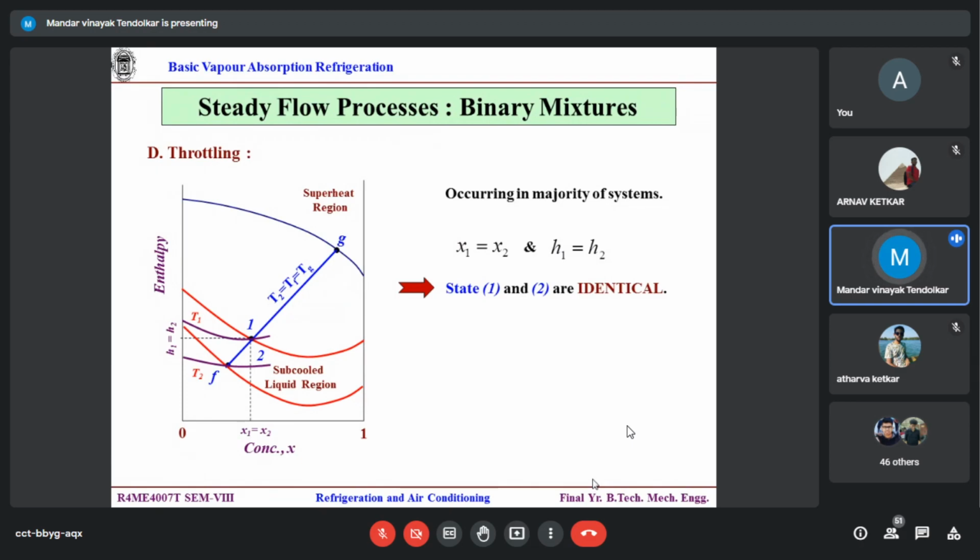What changes is the pressure and the corresponding temperature. Correct? So vaporization may occur during the throttling. That is what we do. In the VCC, vapor compression cycle, also, point 3 is the saturated liquid, whereas point 4 is a two-phase mixture inside the dome. Same thing is happening over here. It is inside the dome.